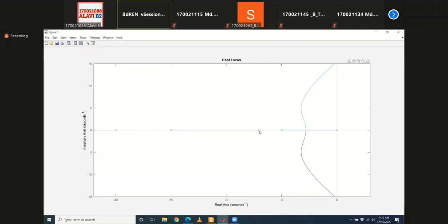It's not that it will go left, it's just that the root locus will exist towards the left of this 0. And this is pole or 0 number 4, even number, nothing exists. Again, this one, pole or 0 number 5, odd number, the root locus exists.